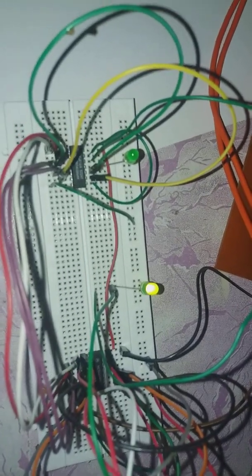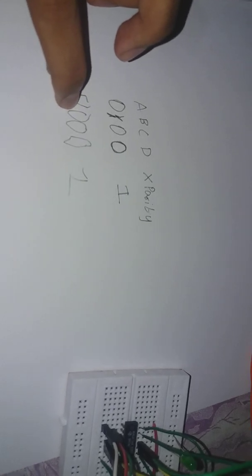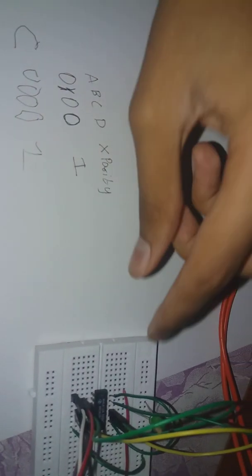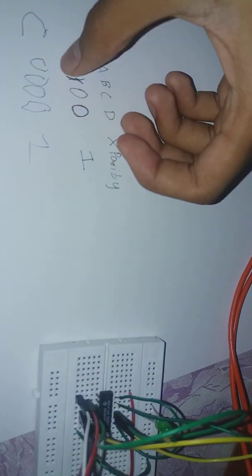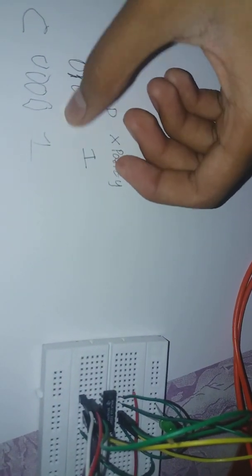As I was saying, if this bit is lost somewhere due to noise effects or some other disturbance in the air or the medium, in any case this one gets lost and this bit becomes 0. So now the checker will check the number of ones in the transmitted bits.